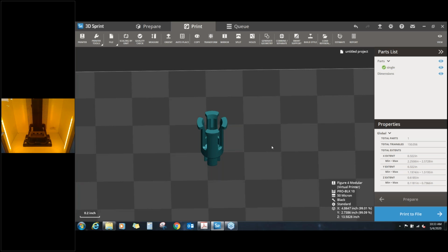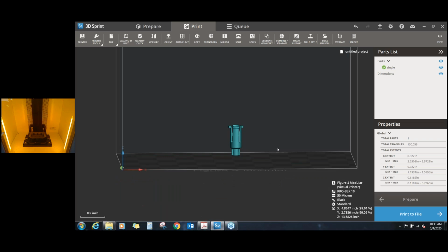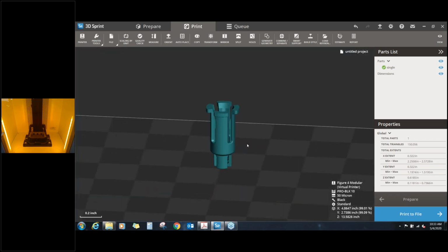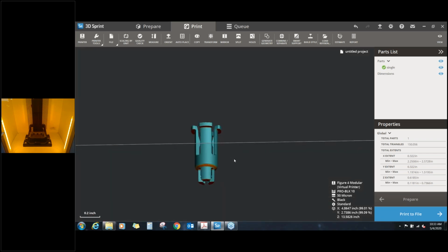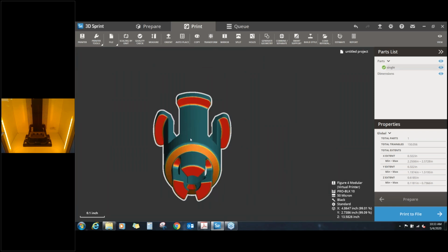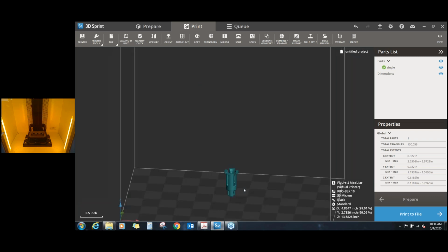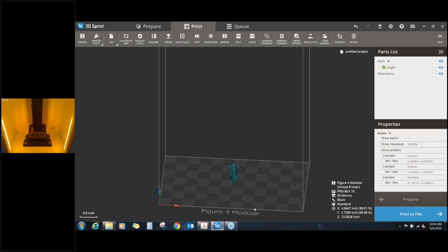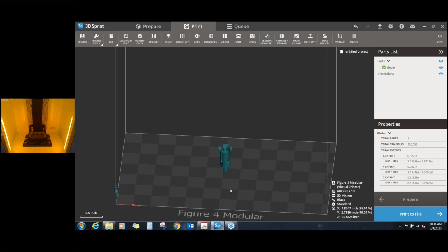So there's a decent chance, a very decent chance, that if we were to print this part in this orientation, it's going to come out just fine, and it's actually going to produce probably the most circular part as well. So we'll give this a shot. If we look underneath, we're going to see some areas that will require some support material. But let's see what we can do in terms of optimizing throughput of this part in a single build of